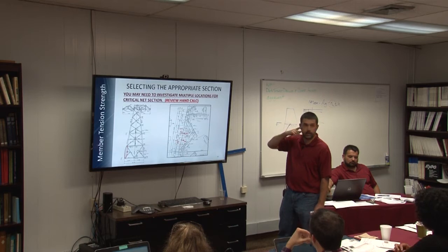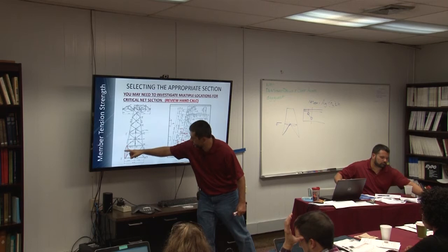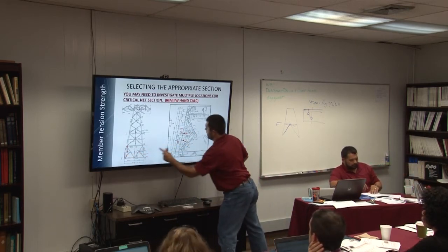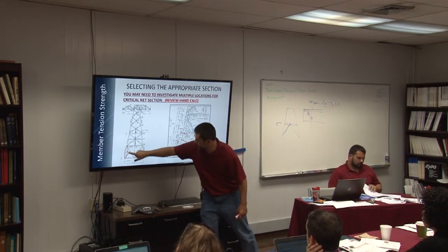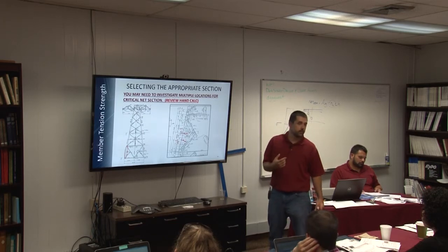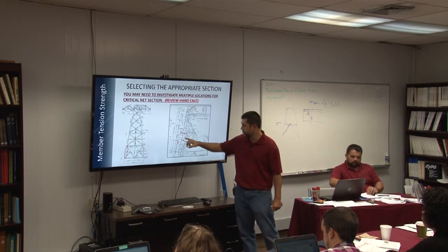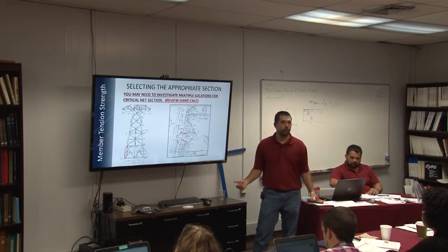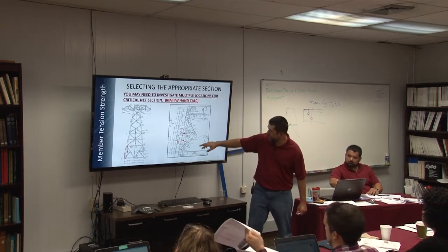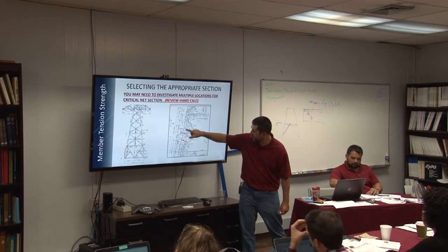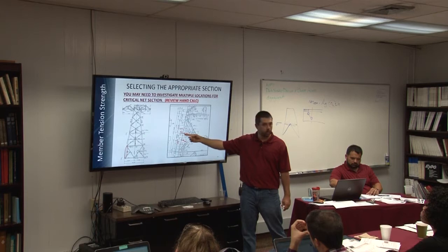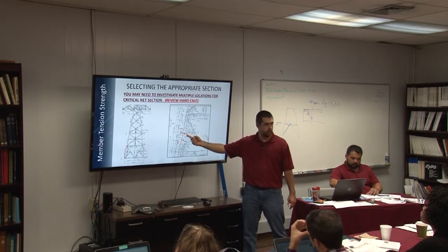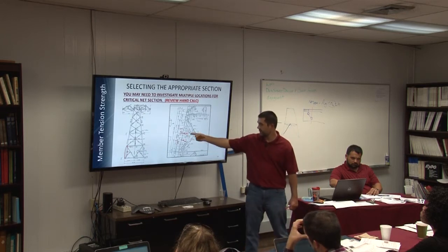Okay. The other thing to think about is I'm looking at this leg member here. Here's the splice that occurs down here, and then this horizontal is this guy. So it's compressed. This redundant member is this guy right here. A lot of times, some of the issues that we see with tower models is that the modeler will only consider the bolts in the connection for specifying the number of holes to remove for net section calculations. However, if I look at the stagger here, these two bolts are on the same gauge line, right? The gauge is 1 5/8 inch, but the spacing of these two bolts is 2.5 inches, and the spacing of these two bolts is 5/16. So clearly my diagonal is less here. This is almost nearly 4 complete holes. There's a small stagger. So this is my weak point, right?